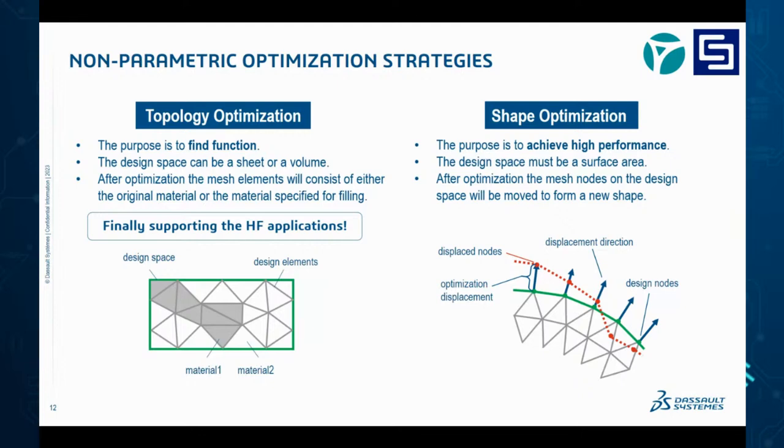Then what we do is specify an area, something like this, from that specific object, of a specific antenna, for example, that we will show later on. And what we do, we warp the geometry. So we change its shape so that we can achieve a maximum or minimize some other goals that we have for this optimization. Okay, so two different strategies to keep in mind.